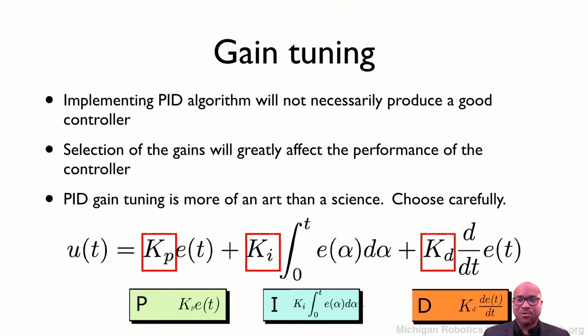Because we should note that what's happening through these gains is a number of things. It is doing an implicit unit conversion from angle displacements, from essentially radians, into Newton meters. I'm going to try to recall that off the top of my head, but into essentially a force. You're going from displacement to force, and so there's a unit conversion that's happening there.